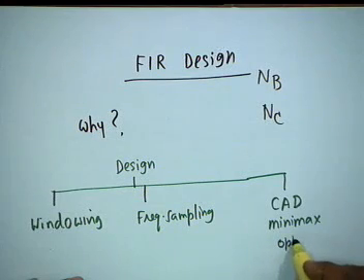You should at least know the term, why it is called minimax. Standard programs are available, very costly programs for design of FIR filters using computer aids, and such designs are called minimax designs because these designs minimize the maximum error. Okay, they are also called optimal in that sense.